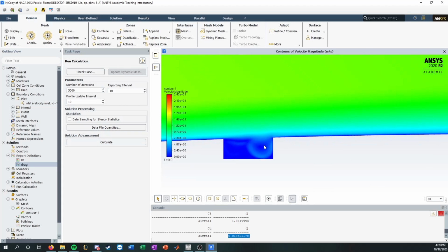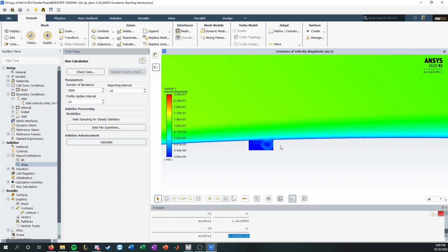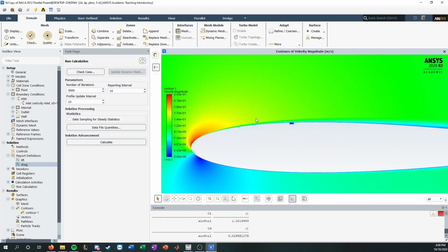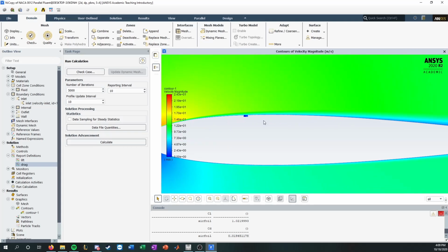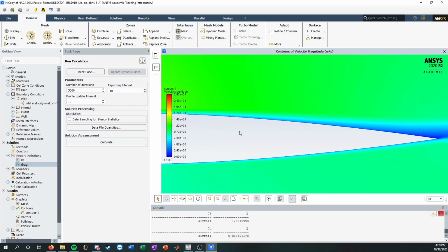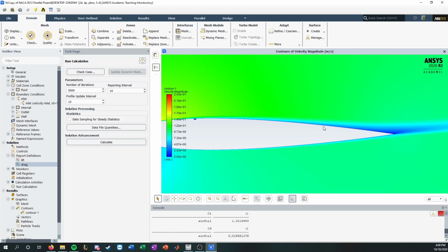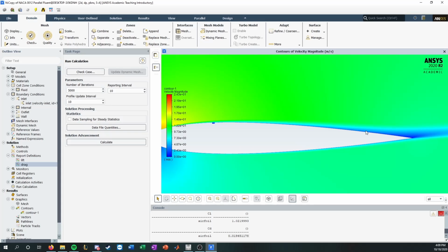If you guys are interested, you could maybe put a velocity inlet and have actually a synthetic jet. You can move this somewhere. So this is more discussion. In theory, if you want to study something, you can move this maybe towards the end. And actually, this is what a lot of people are trying to do experimentally. They're trying to prolong the boundary layer by re-energizing it, by actively putting in energy. That's where you enter plasma actuators. That's the study of compressed jets, and you can add that near the end and see the effects. And so I'll let you guys do that study.